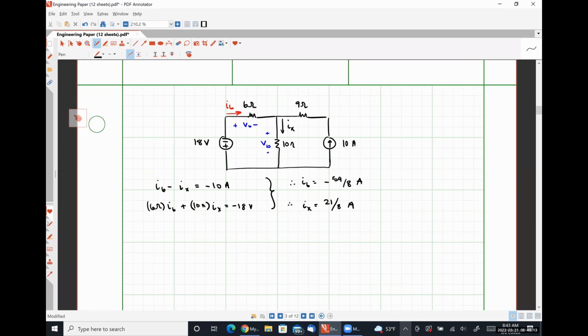All right. So we have found that this circuit containing an independent voltage source, an independent current source, and resistors is an example of a linear circuit because it obeys the additivity property and the homogeneity property simultaneously. Any circuit that contains independent voltage sources, independent current sources, resistors, capacitors, and inductors is an example of a linear circuit. Okay? If it contains dependent sources,